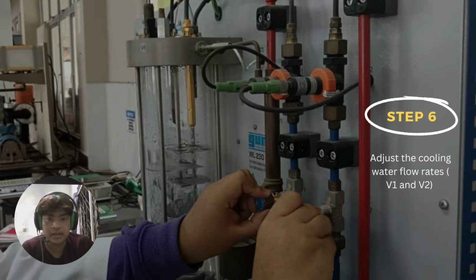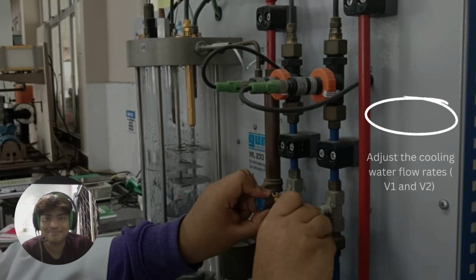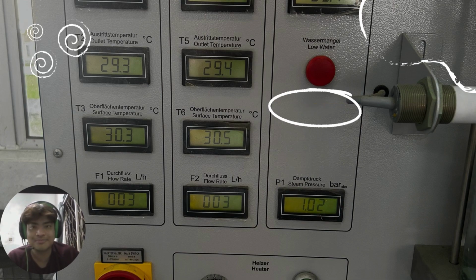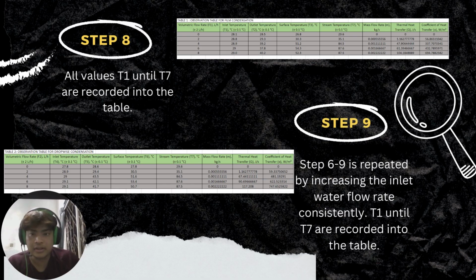Step 6. Adjust the cooling water flow rates V1 and V2. Step 7. Increase the cooling water flow rate by 2 liters per hour, plus or minus, by turning the valve anti-clockwise. Step 8. All values T1 until T7 are recorded into the table.